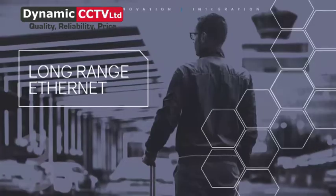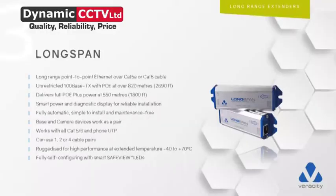So that moves us into our long span. Our long span range is extremely popular. Distances we can achieve with this product, I think it's quite phenomenal. You can go 820 meters, as I said earlier, on Cat6 and still give you your PoE. We can use 1 pair, 2 pair, or 4 pair cables on this. So if you're on some sites where you've got a legacy cable there with a multiple cable connection on it or a loom, you can use 1 pair. You're not going to get PoE off 1 pair, but what you're going to get is a data connection. 2 pairs, 4 pairs, we can give you PoE.